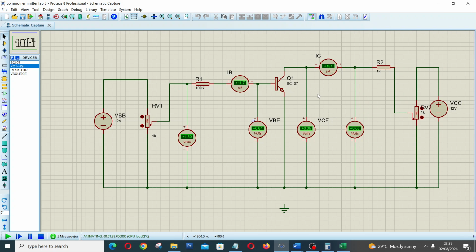When you have taken all your desired number of points, you set this guy to 40 microamps. 40 microamps is what we need. 39, 40.2. So 40.2. So we are starting the experiment from 0. At 0, what is the current that flows? At 0, voltage is 0. Now there's a current of 5.28 microamps. You record it. Then at 0.2, what is the current that flows? You record your current and the voltage. 40.3 is still close to 40.